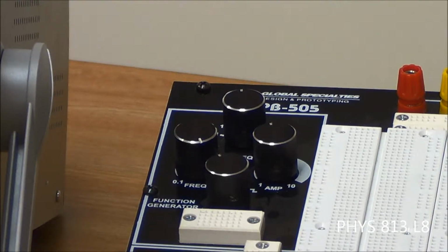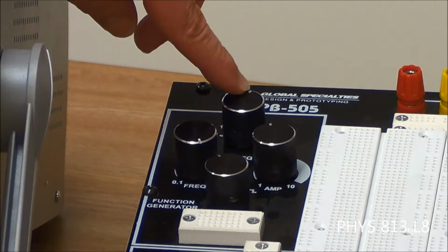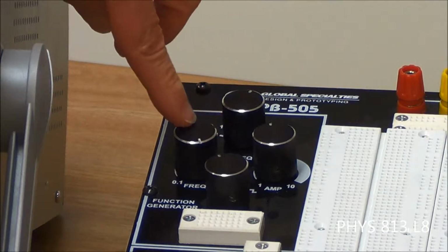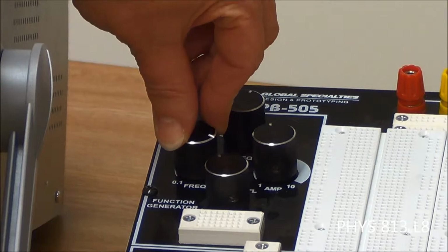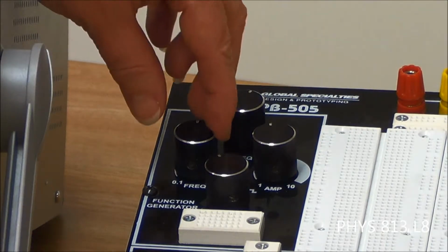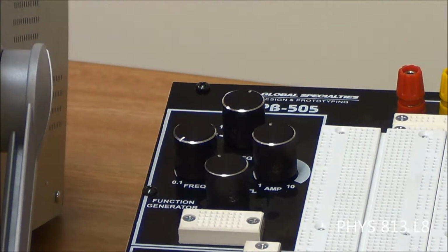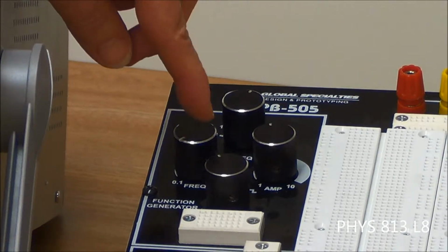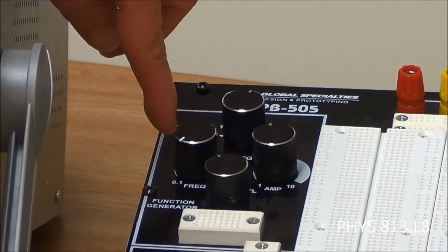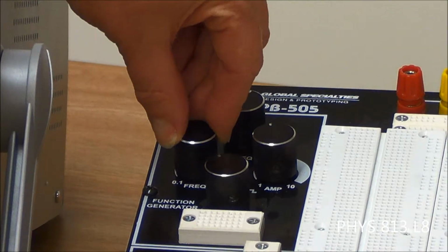So the question is, what do we do if we want a frequency between 100 and 1,000 and there's no position there? So we set this back at 1,000, which is 1 kilohertz. Then we can turn our continuous moving knob down, which is counterclockwise. As we turn it down, the frequency it's producing gets less. And if we turn it all the way down to here, which is 1/10, then 1/10 of 1,000 is 100. So we can change from 1,000 down to 100 with this top one set at 1,000, and then this one we can vary.